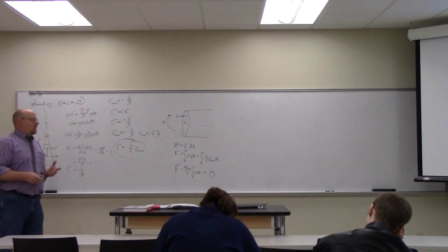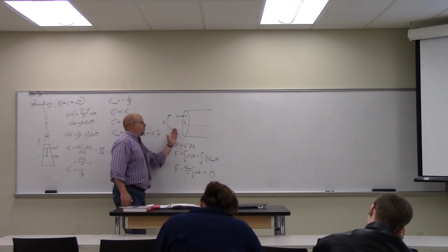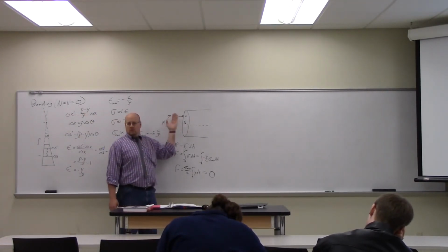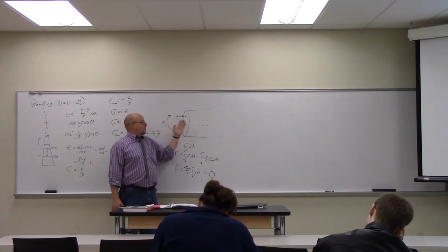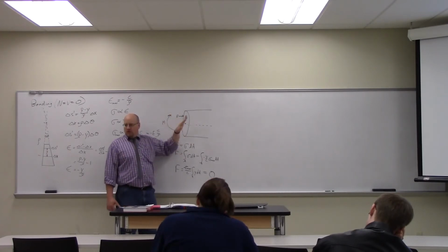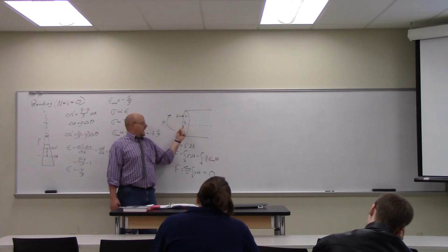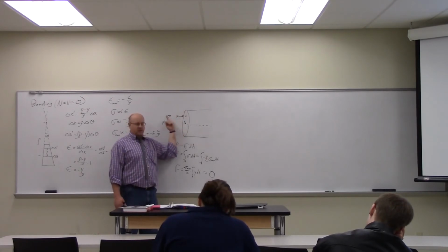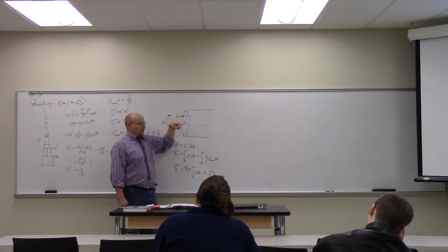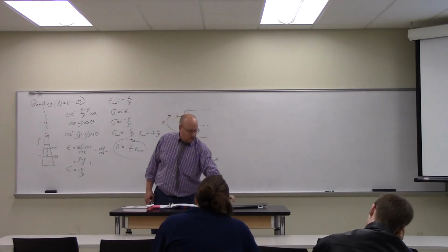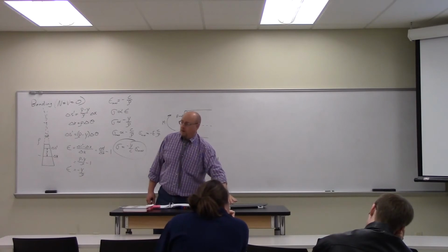Now everything we're talking about in this section assumes that we have symmetry in the direction into the board, in the z direction. So we actually pass through the centroid in both directions, because since it's symmetrical, the axis goes through the physical center of the z direction and then the centroid of the y direction. So if this is a triangle, like you'll see we have in our first problem up there, right?